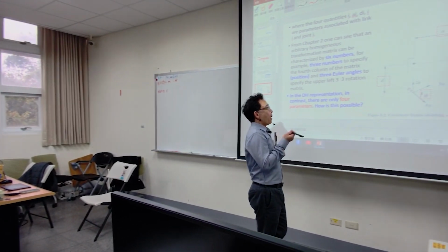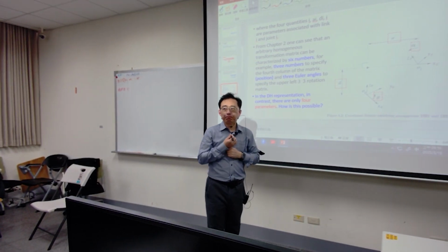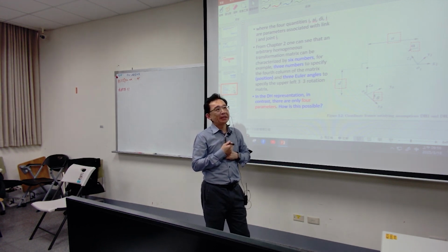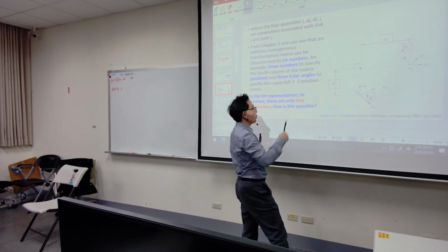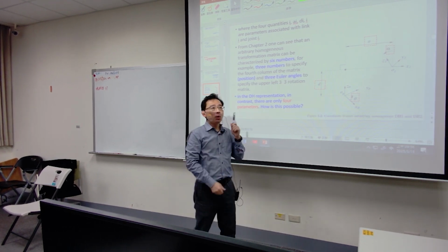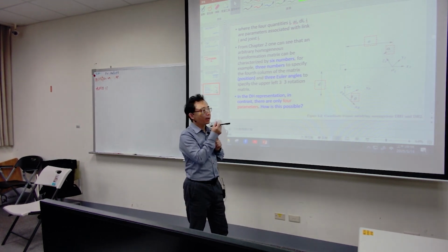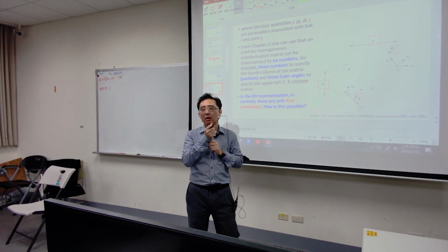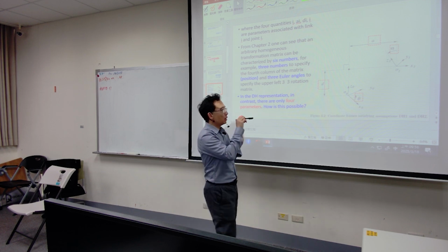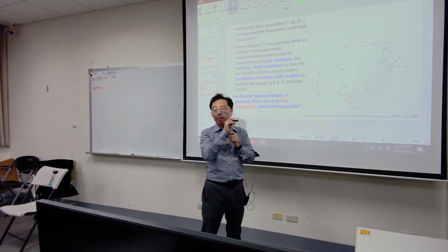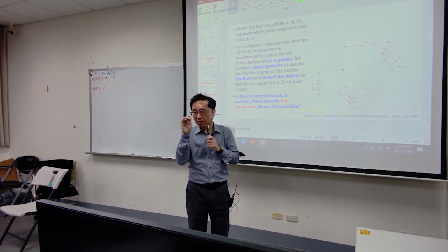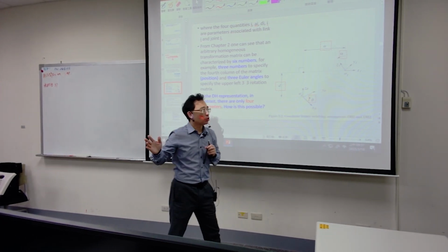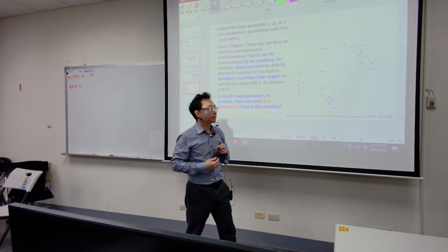So let's go back to our figures. We are not finished yet. I want to go to the next joint, joint 1. Between 0 and 1 we have a D and we have an A. The alpha is hard to imagine. We don't care about the rotation axis at this point. We care about the next joint's x-axis.